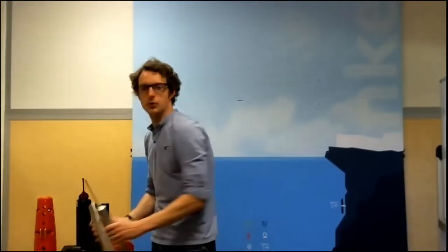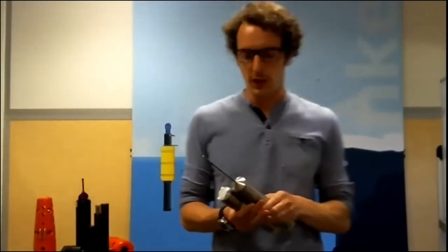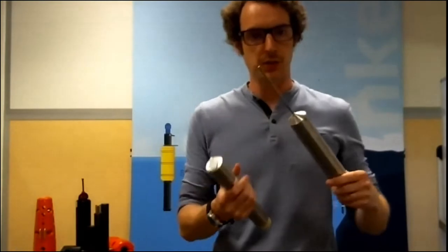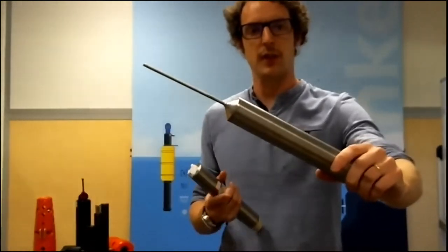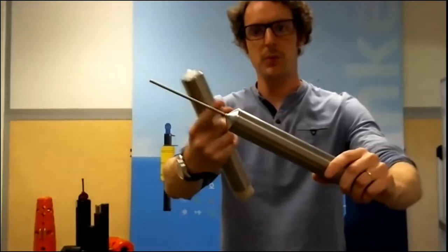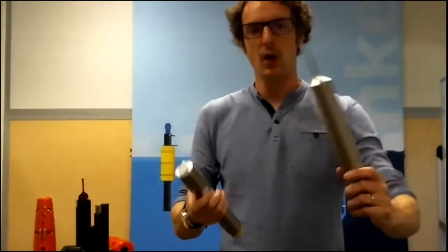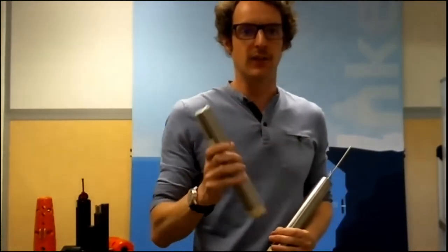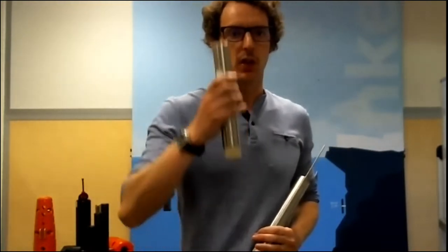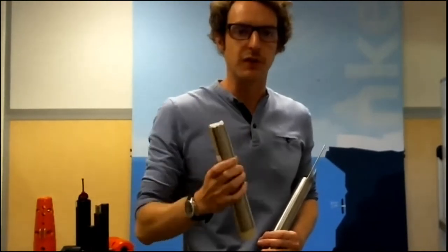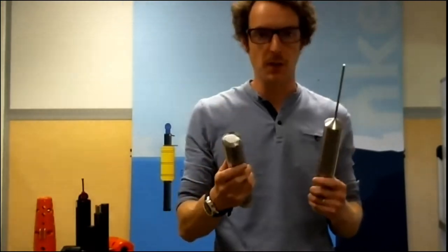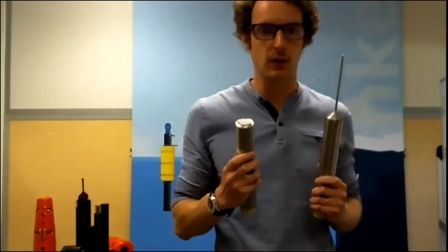And then we're going into the deep sea instruments. So we can measure whether temperature and pressure, or accurate temperature with the temperature sensor that is out of the common body to be able to measure accurate temperature, or this specific Ysense that is called Ysense AD, that stands for acceleration and depth, and that is dedicated to a specific application. It's to monitor the acceleration of free-falling elements, and more specifically piston cover. So these instruments are in titanium housing and depth rated to 6,000 meters.